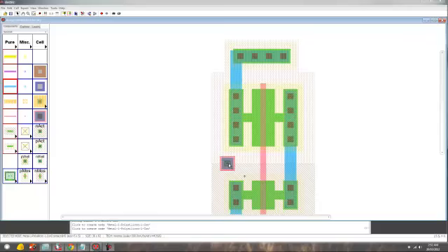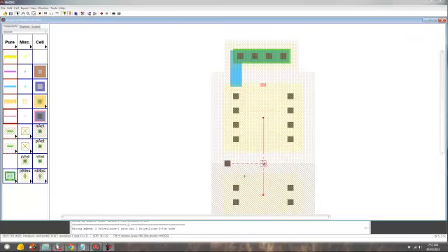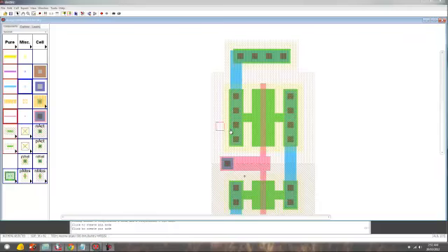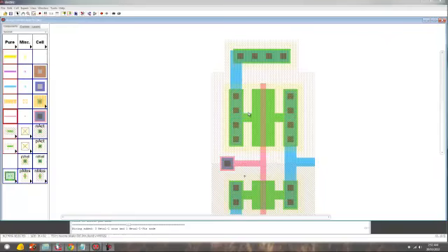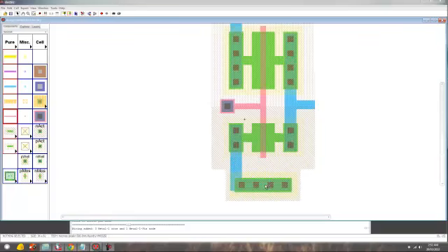Add in a metal at the left side, and this on the right side. Connect it, right click, change the width of this, Ctrl I and change it to 2. So now we have to name this, export this. So select it, press Ctrl E and name it ground.